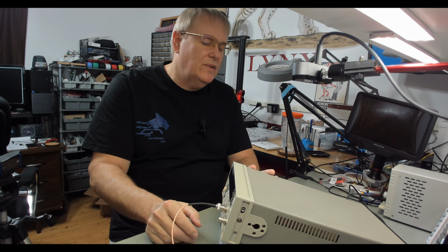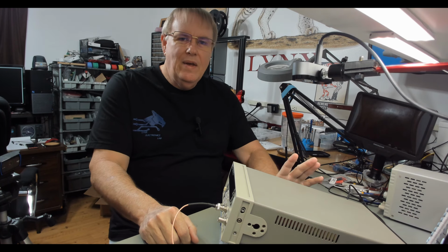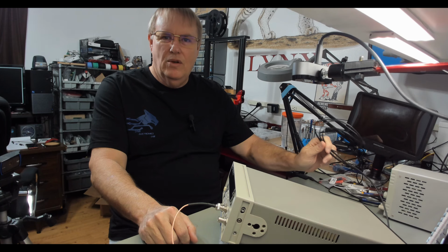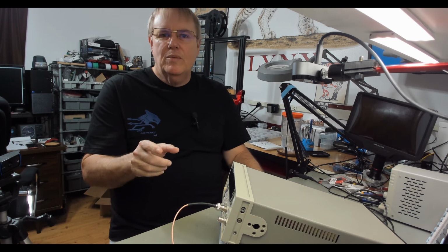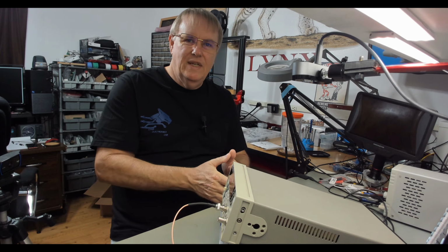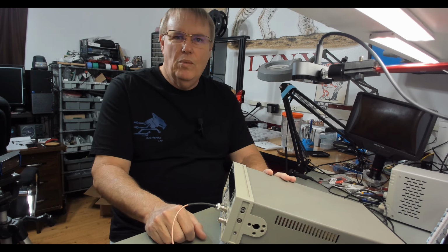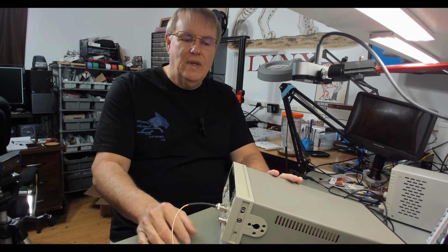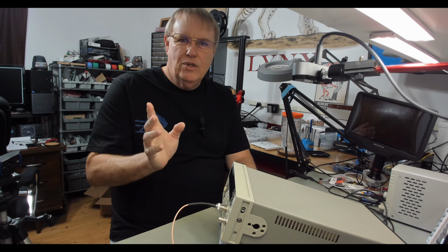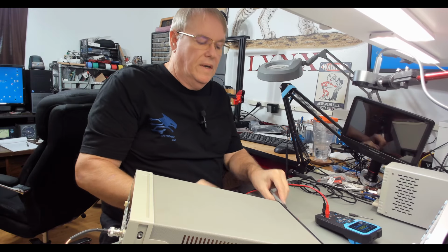So I have a theory what's going on, and this is the point where I decided to bring you guys in. I'm wondering if this is not really needing to be a null cable. What I'm going to do is a quick little test. There's a way to test the COM port and see whether it's a DTE or DCE. If this is a DCE, it means we shouldn't be using a null modem cable. So that's probably all the problem is. So let me get set up here on the bench. We'll check that, and I'll show you how I'm going to check that serial port, and then we'll go from there. Okay, I got set up on the bench.